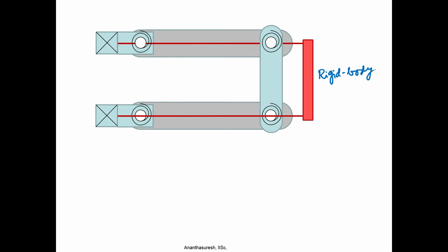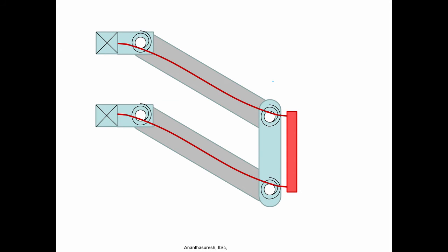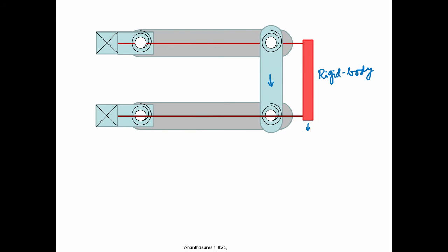If you have that, when you apply force over here or the corresponding pseudo rigid body model where you apply a force there, it is going to deform like this, okay, where the beams are bending, and you can see that this red rigid body moves in that direction as well as in that direction.